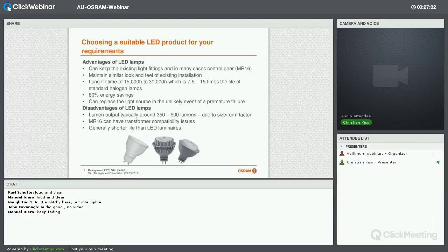The heat sink obviously can only be so big to draw away the heat that is generated. So that limits how high the wattage can be and how high your lumens can be. Naturally, over time, as the technology matures and efficiency gains are made, the lumen outputs should push the envelope a bit and get higher. But that's typically where we're at now.